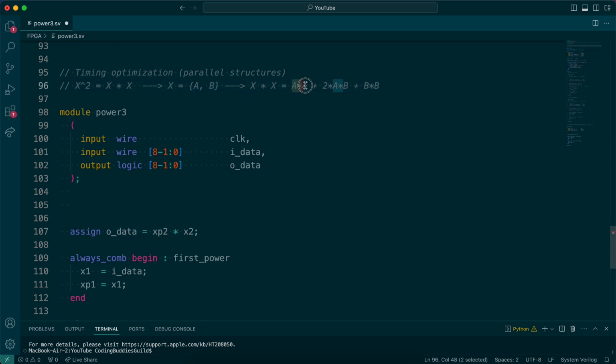We are breaking this up because this is an 8-bit multiplication and it takes time. So I'm dividing that into 2, or in this case 3, and if these were different, that would be 4 max. 4 by 4 multiplication. 4 by 4 multiplications are much faster than 8 by 8 multiplications. So this is going to be a faster design in general. This is the whole idea. And then once I have this, I can shift this 8 times and shift this 4 times and then add it with this. This is how it works. So this is what we want to do now.